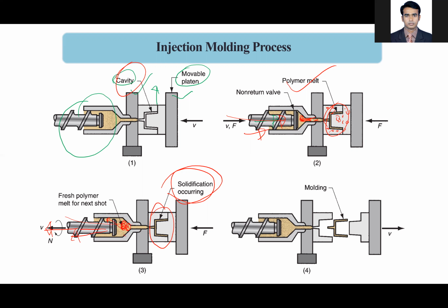Once the pressure is attained, we move the movable platen outside and take out the material. Since there is only environmental pressure and no excess pressure, the material is not coming out; it just stays in there unless we start pushing again. So it is a discrete process. Once a part is made, we take the part out, then we close the cavity again and get another stock of material.